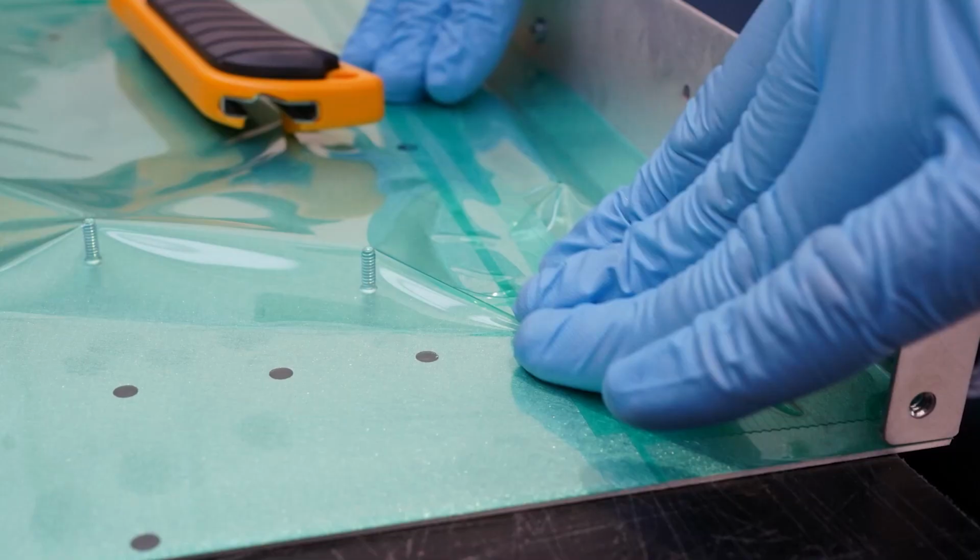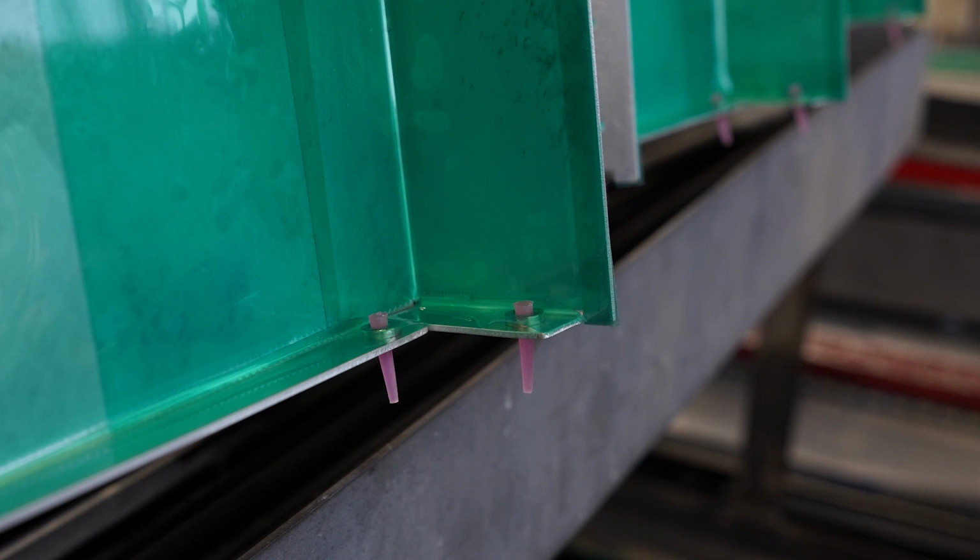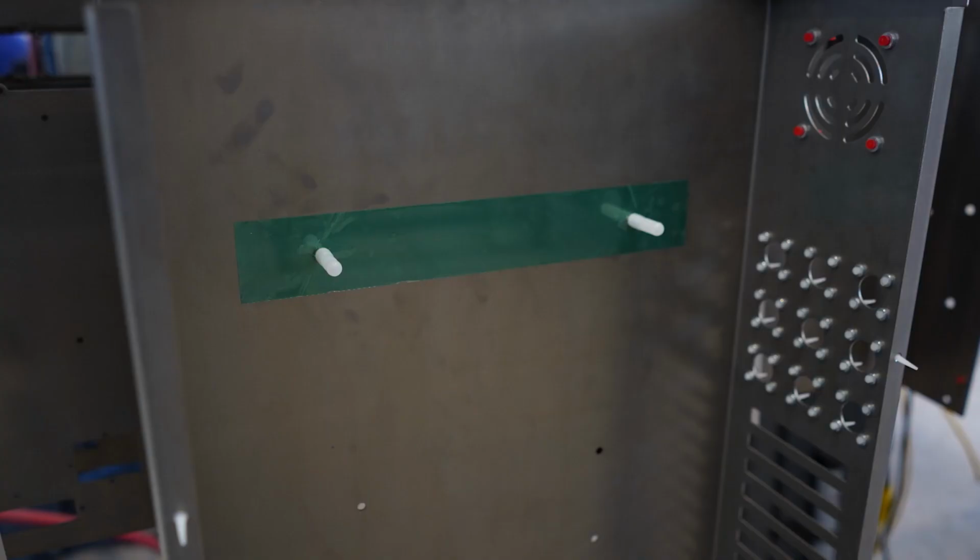With masking, you have a few different options. You can mask the entire inside of an enclosure, mating surfaces of an enclosure, or areas surrounding connector cutouts, or areas under electrical components. As a rule, Protocase masks all internal and external fastener threads using silicone caps and plugs. We do not currently offer masking the inside edges of a cutout. Instead, you would need to mask both sides of the cutout.